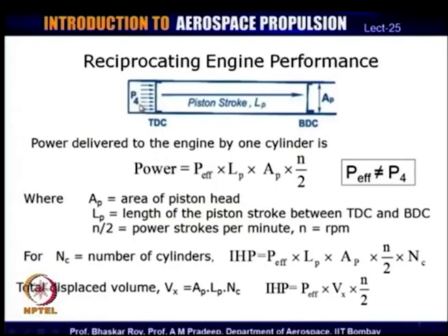From the cycle diagram we have seen that, and this pressure is very high. It is also hot gas of course. As a result, it exerts a lot of force on the head of the piston, often called the piston head, and this has an area. Obviously, the more the area of the piston head, the more likely the force, but as we have seen the aircraft engine has certain limitations of size and weight, and as a result the size and weight are often a little restricted. So, the pressure here creates the force which then starts driving the piston through its power stroke.